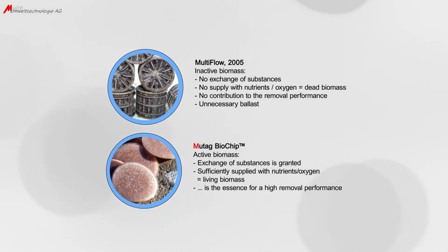As you can see here, both carrier types contain biomass. The tube-shaped carrier is completely stuffed with biomass, whereas the limited diffusion depth of 0.5 mm will take its toll. Only 0.5 mm of all the external space is occupied with active biomass. All deeper layers cannot be supplied with nutrients and oxygen, since the biofilm is simply too thick to be supplied.